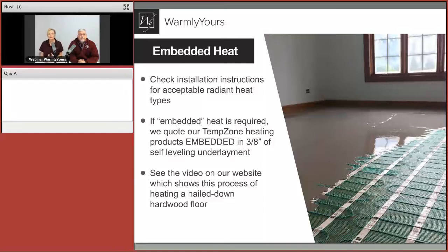Right. So you can do thin set, or you can do self-leveling. The reason we really recommend a self-leveling product is the heating element is completely encapsulated, and there's no trowel, no really sharp troweling going on. And then if for some reason you want to change the actual flooring surface, you want to go from tile to a floating wood, you can do that easily.